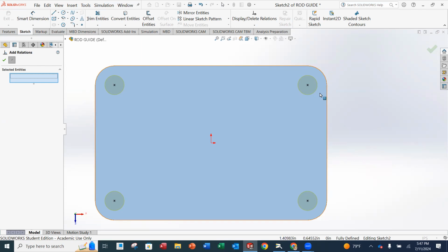Because that's really all that we did by identifying that center for that placement. But I don't need to do that for mine because mine are already there. Okay? So again, you want to activate that radius when you're placing it. Don't click it, but then you click at its center. And then that way, the center of the hole shares the same center as the fillet, which is exactly what we want here. Okay. All right.